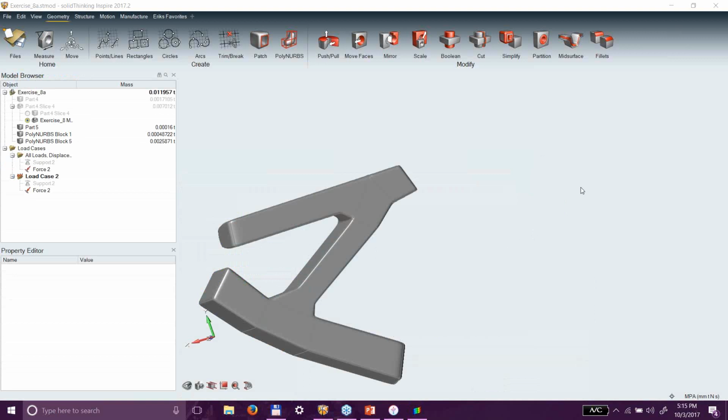We understood how to get around in Inspire, understood the concept of the multifunction icons, the ribbons, bringing geometry in, setting up an initial analysis, getting those constraints, those load cases, all that sort of fun stuff going, getting an analysis run, taking that geometry and converting it into a nice design space with non-design spaces as necessary, setting up the optimization parameters, running our optimization, looking at the results of the optimization, reanalyzing those results, and then potentially even creating NURBs from it. And that's it. I know it's been a little bit rushed.